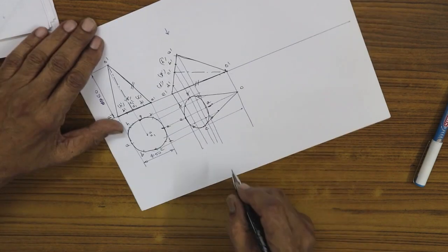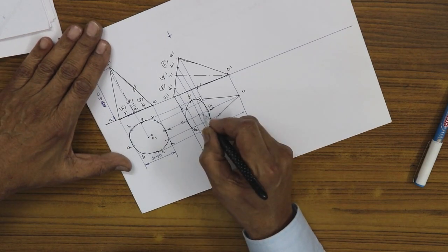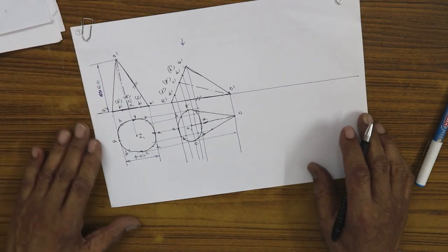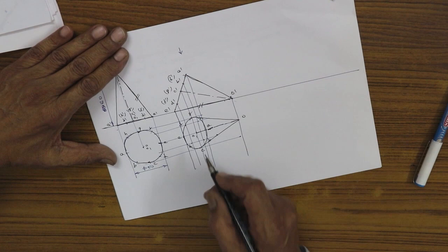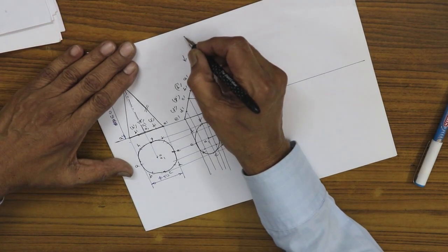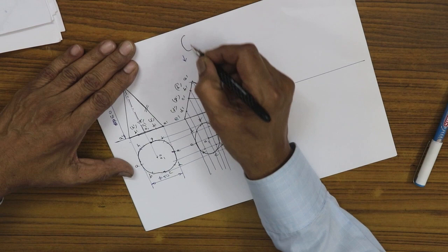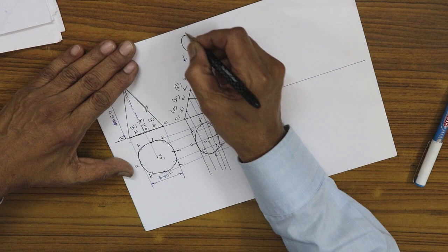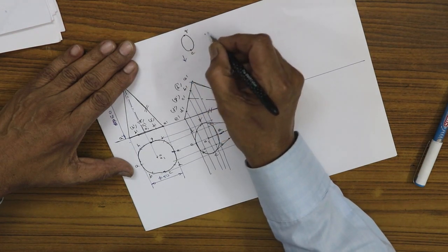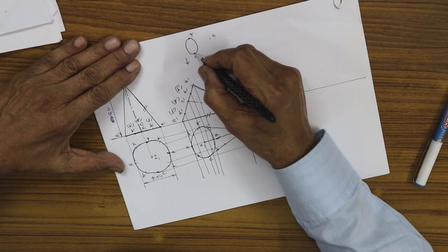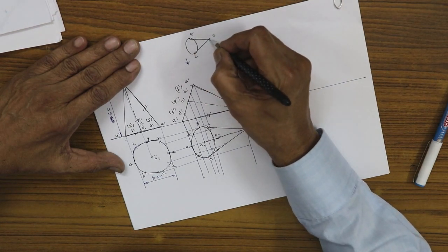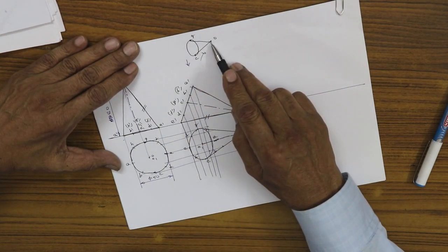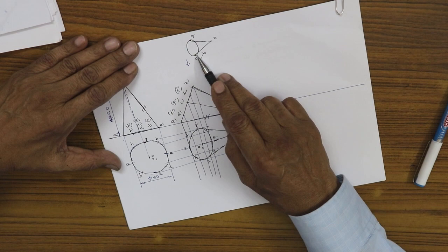Because the cone has got an infinite number of generators. We have an axis long and short, which is actually O1. Now, I will give a small piece of information at this point of time. I have seen students drawing the ellipse. We have an extreme point here C, an extreme point here G, and O. Never join OC and OG, never do that. This is wrong.